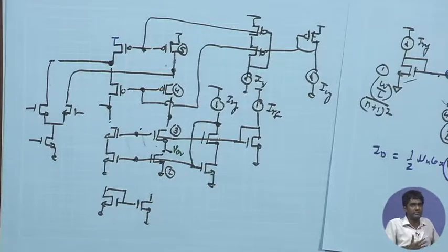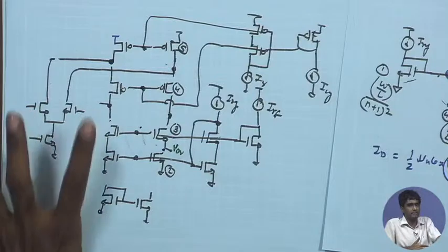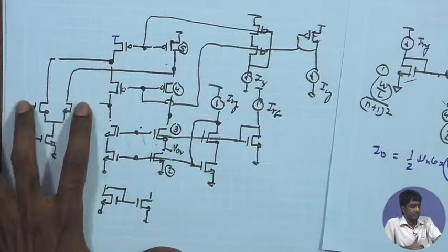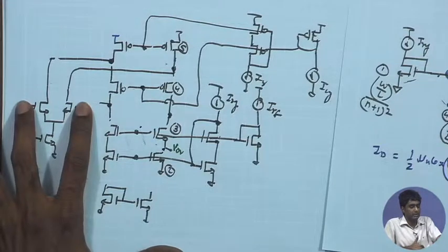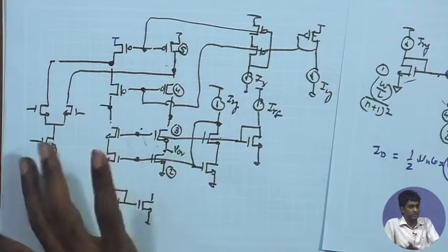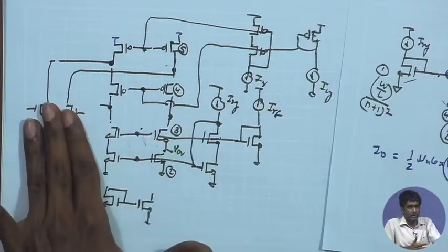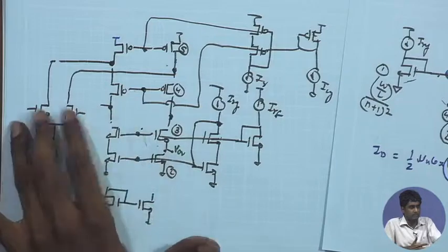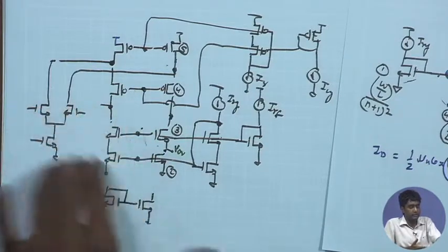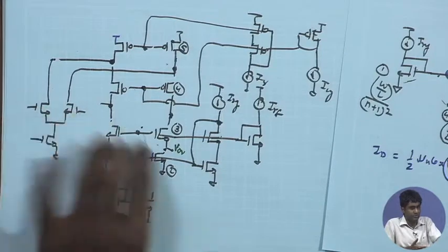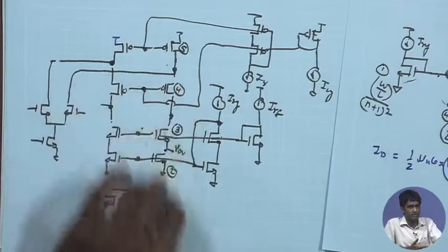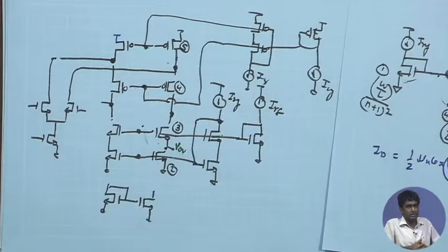Noise consideration again becomes important, because from the noise point of view, just like our earlier case, the noise enforces a larger GM at the input device, and the GM of the second stage devices are not important. So, there the 1 upon GM ratios come in the overall input referred noise. The GM1 of the input pair comes in the denominator, all others in the numerator. So, we would like to have a larger GM over here as compared to the stage at the output transistors.